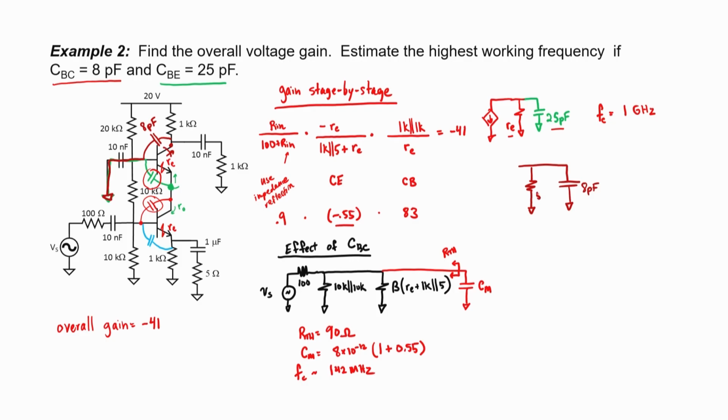In other words, 500 ohms coming from this resistor, and that's connected to the collector of a transistor. So from the perspective of the capacitor, we see a low-pass filter. If we use 500 ohms and 8 picofarads to calculate the corner frequency of this low-pass filter, then we wind up getting a number around 39 megahertz.